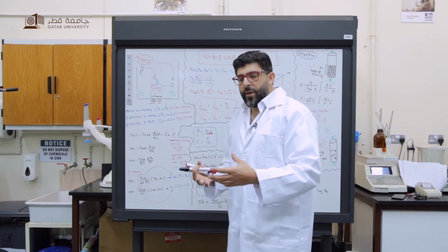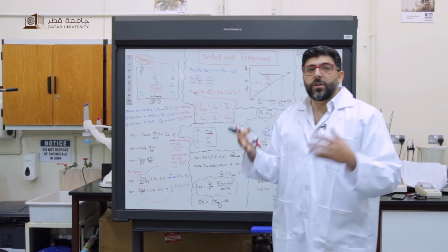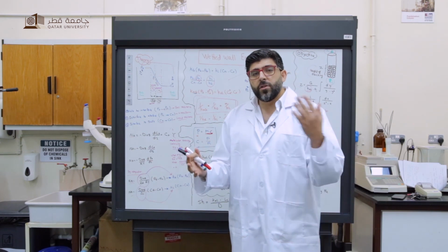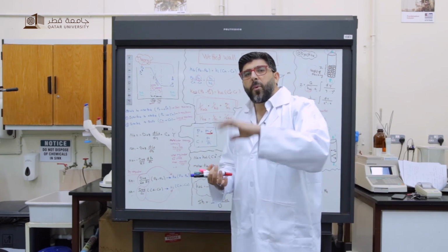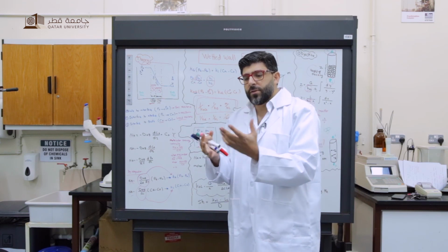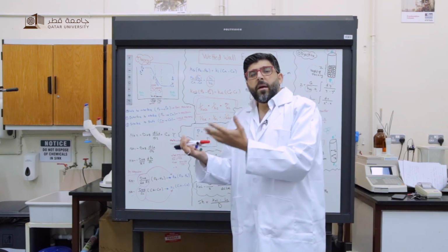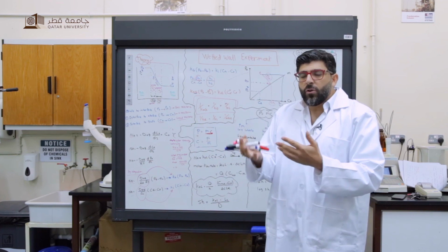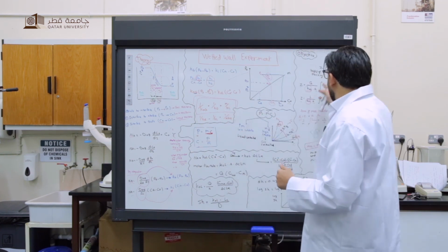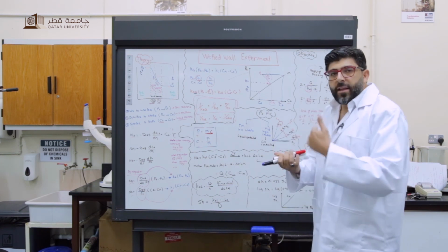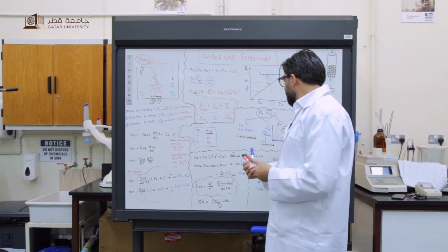We purge the water with nitrogen gas and strip out the oxygen, so the liquid is less in equilibrium with oxygen. When it contacts oxygen in the column, it can reach equilibrium again.